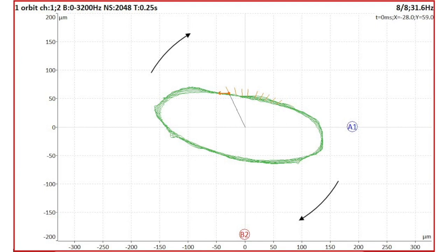Now you certainly would ask me why the key phaser positions are not in the same place. It is because of the data. It is the run-up record. That is why the positions are shorter and shorter. You can see the shaft position is 0 microns on both axes. We do not use the DC channels, just only the AC channels. It means that DC part was removed.